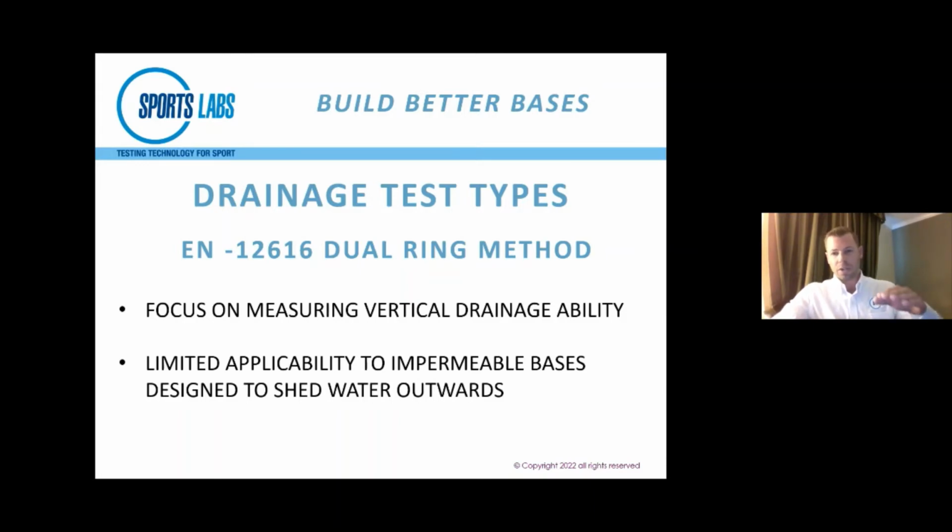So say, of course, these bases are built with different layers. You might have a cap layer of fines or finishing layer. We can verify that drains, and if that drains and we still have a drainage problem, then we can dig that part out and move on to the next layer, and really, in an investigation sort of way, see where the problem lies. And then even just beyond the base, we can do this at the surface as well and work our way down. Here's another photo of that.